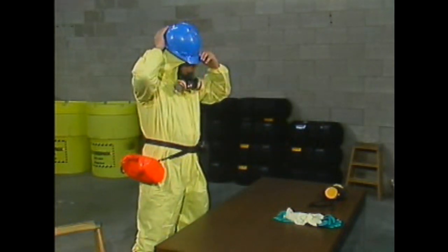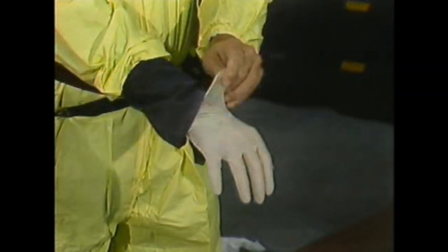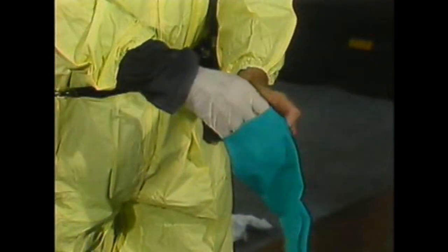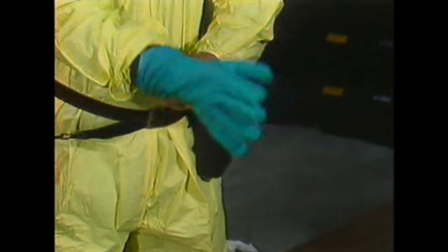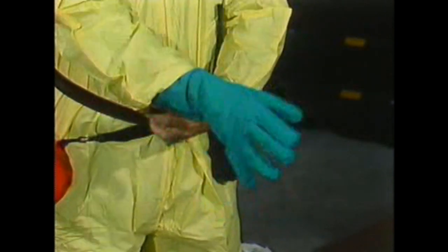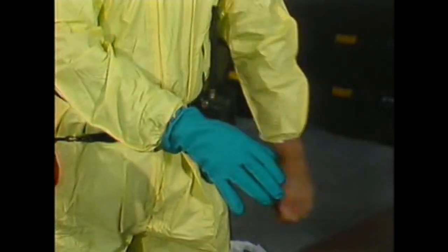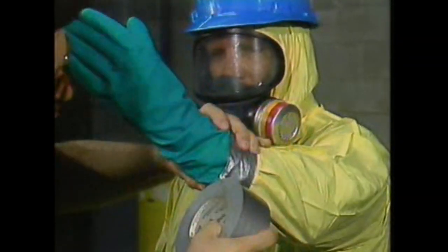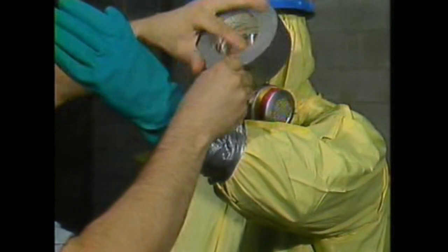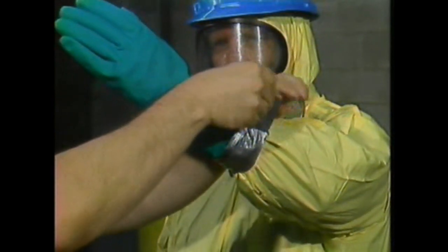Another part of protecting your skin is wearing the appropriate type of gloves. Again, it's important to select the right type of protection for the job. The gloves protect your hands the same way that chemical-resistant boots protect your feet. For additional protection, inner gloves are often worn under the outer ones. When you're wearing chemical-resistant clothing, your sleeves and gloves should overlap. This will prevent exposure to airborne particles and any liquids that could get inside the glove. Sometimes, sleeves are taped to the gloves to form a seal. Tape can be hard to handle when you're wearing gloves, so you may need help taping your gloves and sleeves together. And don't forget to add tabs to the tape. They'll come in handy later.